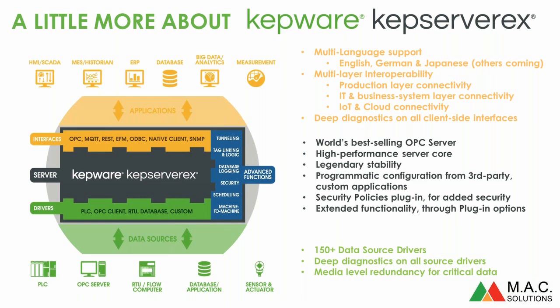So there's also deep diagnostics on the client side interfaces as well. Again, you can filter the OPC diagnostics down to a particular client connecting to a particular device. If you want to, you can filter it down by lots and lots of different levels.